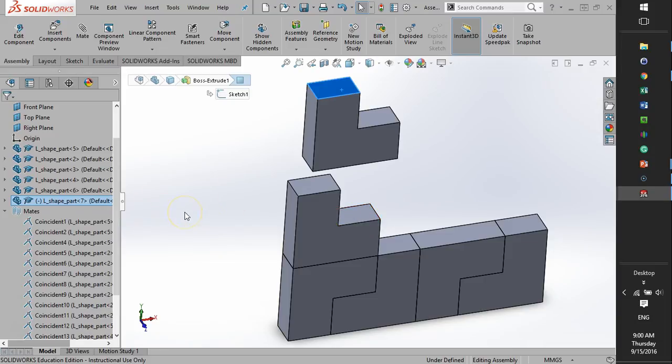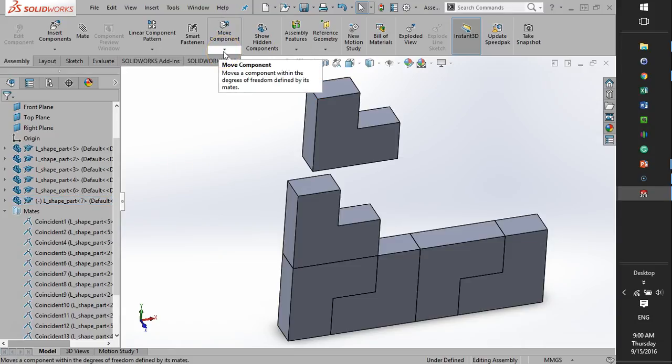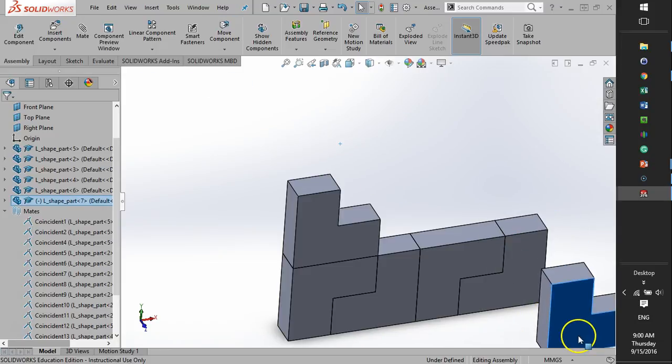But for more complex parts and assemblies, it can become quite challenging to rotate and mate at the same time. So my general advice is try to get the part in generally the correct orientation and then add the mates. So I don't want the part over here and be like, oh, I want to mate it to this somehow. Then it becomes pretty tricky.